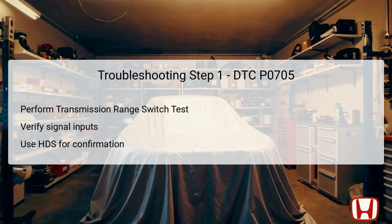The first step in troubleshooting DTC P0705 involves testing the transmission range switch. Begin by verifying the input signals of the range switch using the Honda Diagnostic System, HDS. This tool allows you to compare the signals received by the TCM against expected values for each gear position.